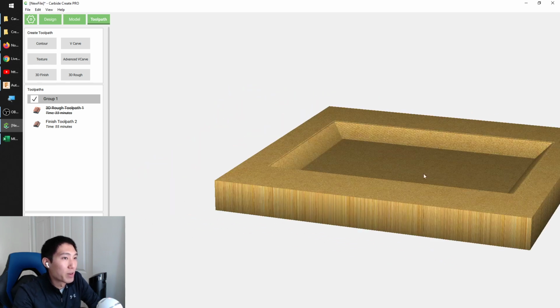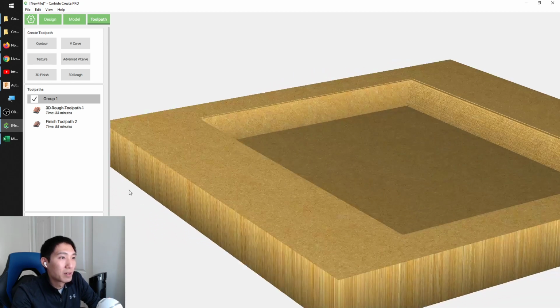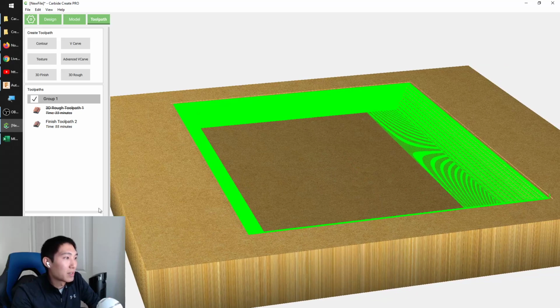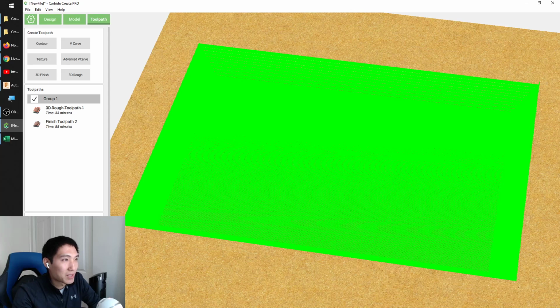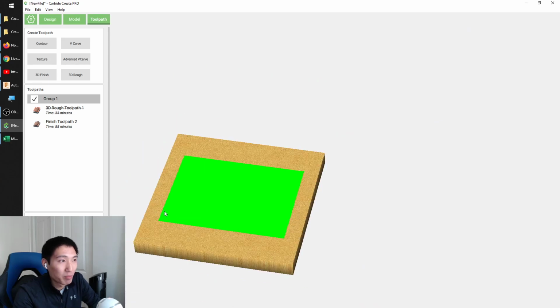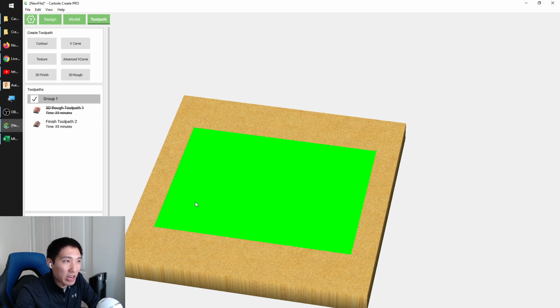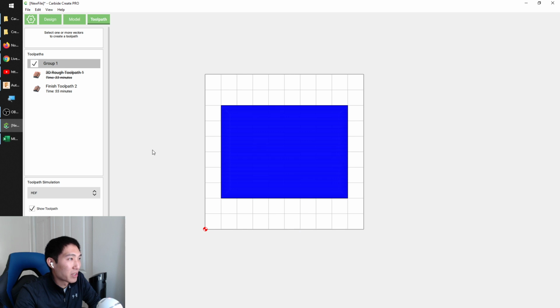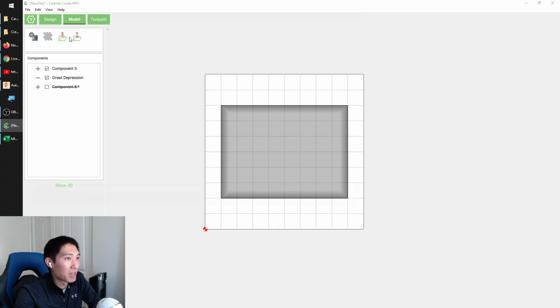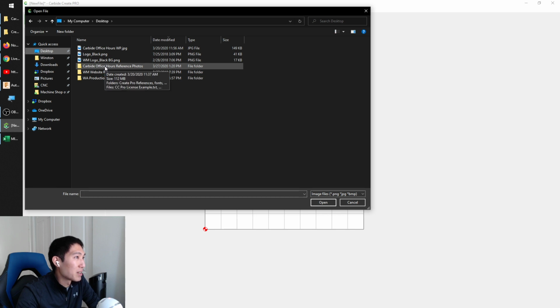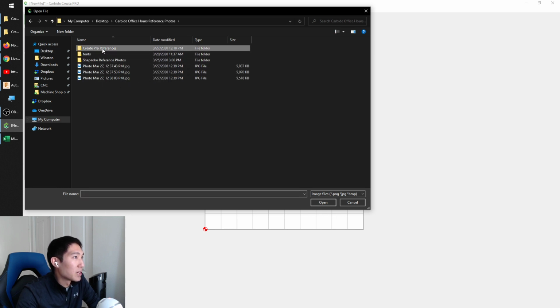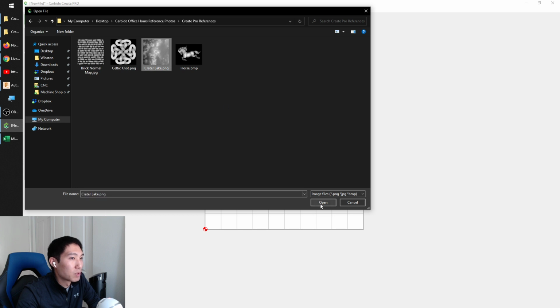And that's going to just have the toolpath go back and forth in lines to create the pocket. So that's basically Carbide Create Pro in a nutshell. There's a lot you can do with it just because you're adding shapes in an infinite number of combinations. Another thing you can do is make a topographic height map. So instead of importing something fixed and whatever aspect ratio you want, I made a square crop of a terrain map. Well, it looks like that.